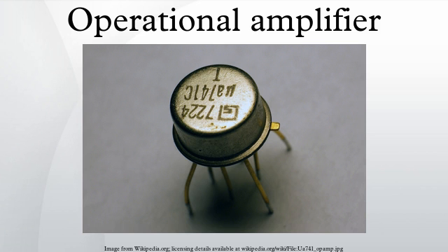The description of the 741 output stage is qualitatively similar for many other designs, except some devices are not internally compensated. Some modern devices have rail-to-rail output capability, meaning that the output can range from within a few millivolts of the positive supply voltage to within a few millivolts of the negative supply voltage.